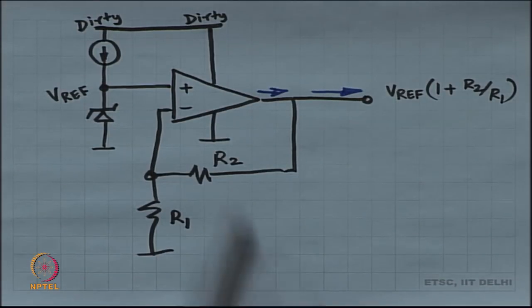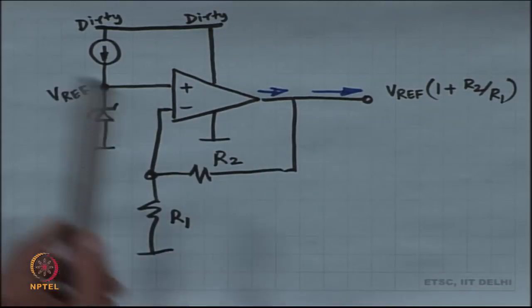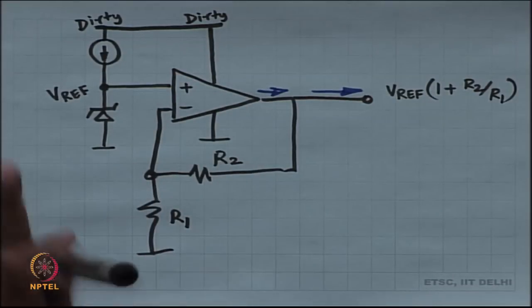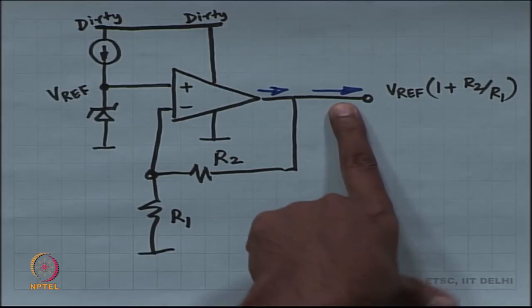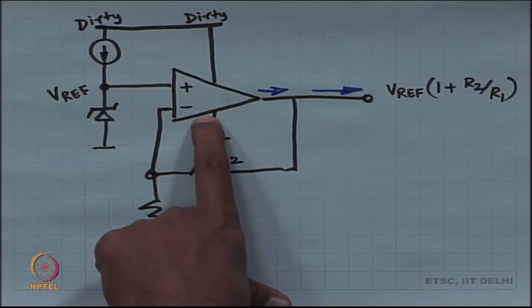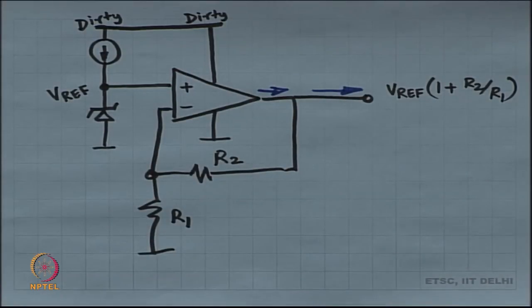What people do is, this circuit works, but it can't drive a strong load. It can drive only as much as the op amp can provide. The op amp output current is somewhat limited, you have to design the op amp. So, that op amp, differential amplifier, all of that, the output current that is coming out of the op amp typically is not very large.